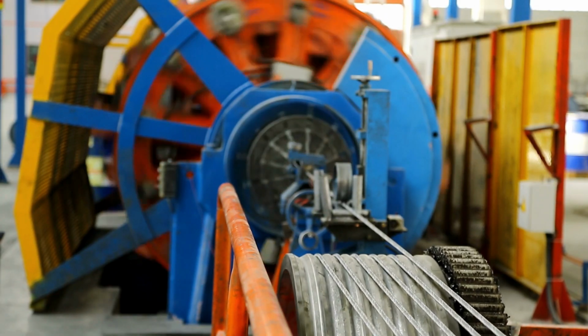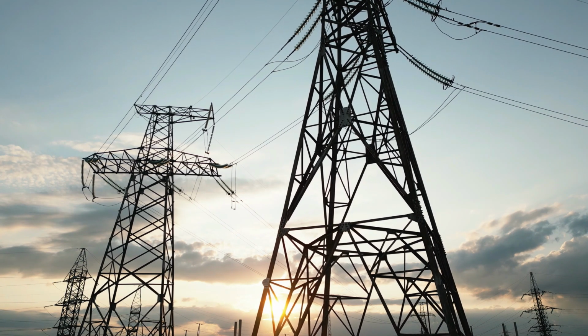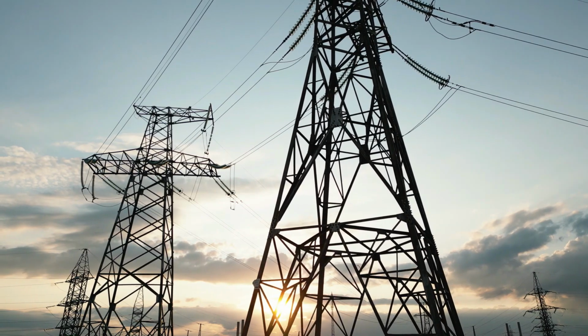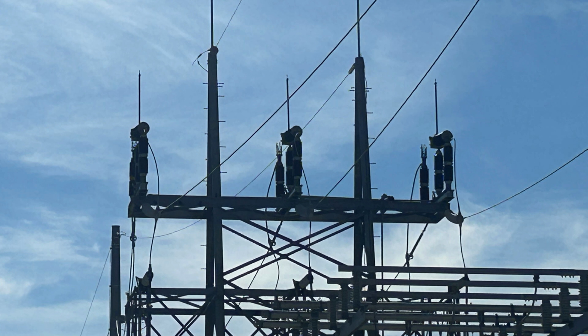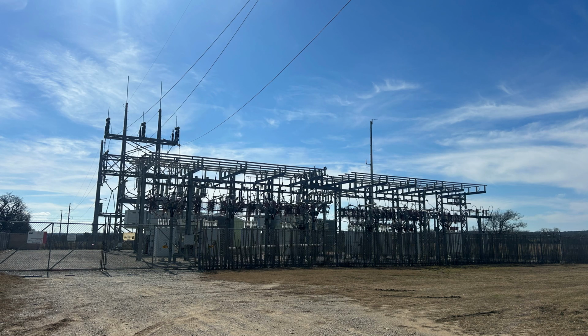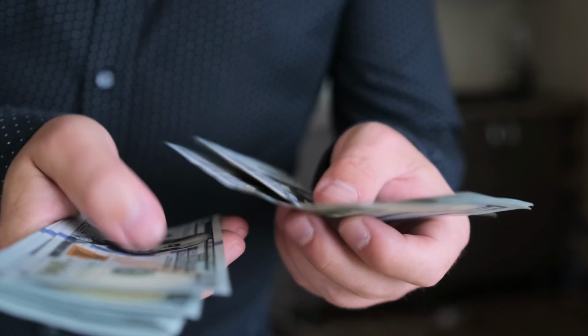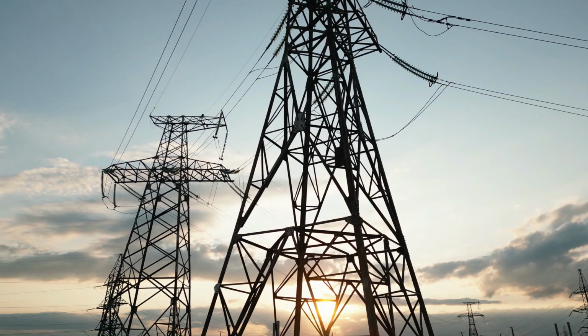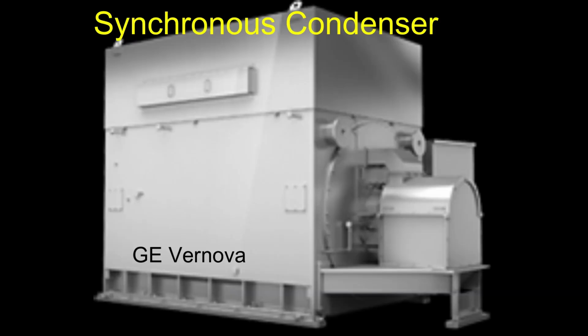Besides simply costing the user more money, low power factor increases the current in electrical distribution lines, which leads to higher energy losses and a greater strain on transformers, conductors, and other equipment. To address this, utility companies often charge industrial and commercial customers with low power factors additional fees and penalties. These customers can improve their power factor by installing power factor correction devices, such as capacitors or synchronous condensers, which offset the reactive power in the system. By doing so, they reduce the overall current flow, lower energy losses, and they avoid costly penalties.